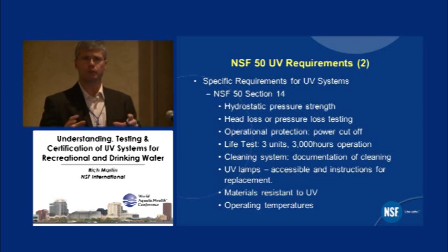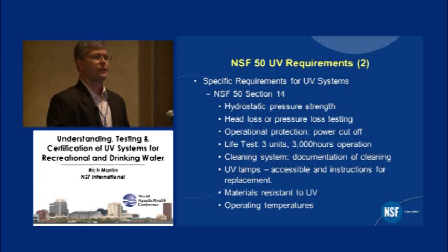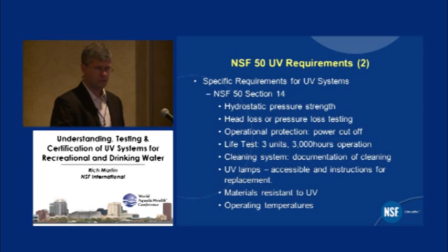And beyond that, there's additional testing, essentially this life test. So you take 3 different ultraviolet light systems and operate them for 3,000 hours, about 4.5 months. And then after that, go through performance testing on it to actually confirm the disinfection efficacy. There's also cleaning system requirements and other details.